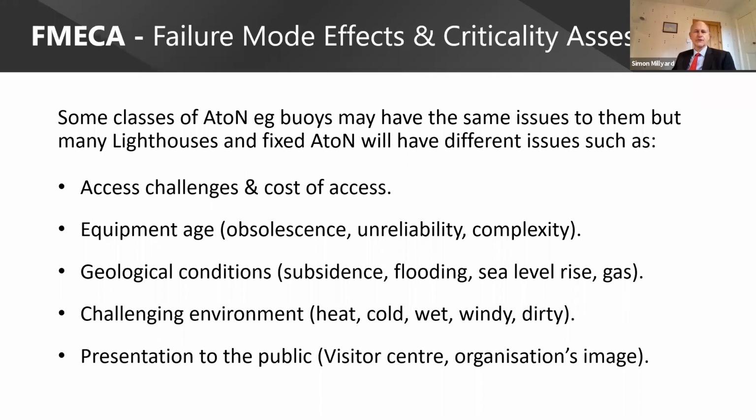You might do as a manufacturer; they may choose to do this when they're designing a circuit board or something. But for an AtoN authority or provider, as a competent authority delivering AtoN navigation, you would look at systems and say, well, if this failed, what is the mode it would fail in? What is the effect of that failure? And how critical is it?